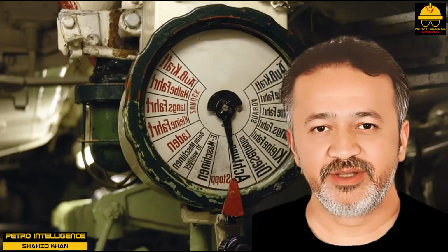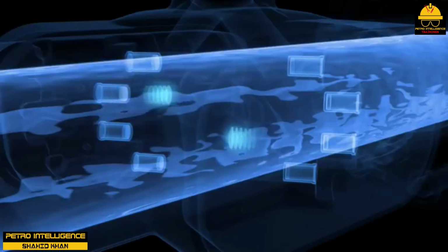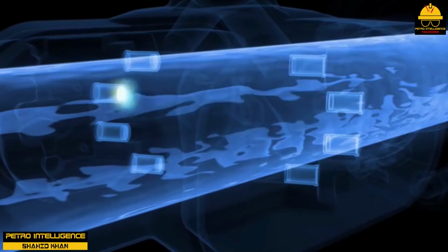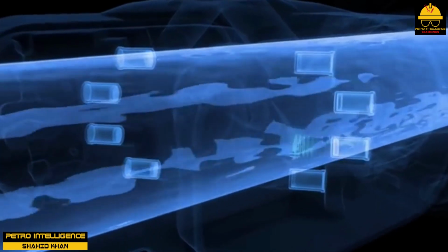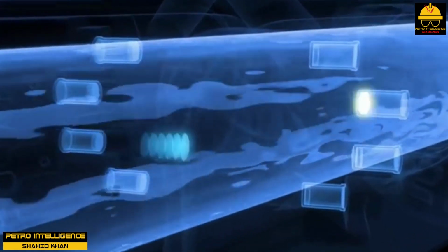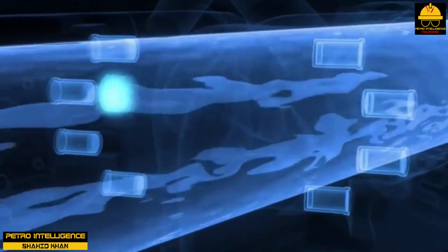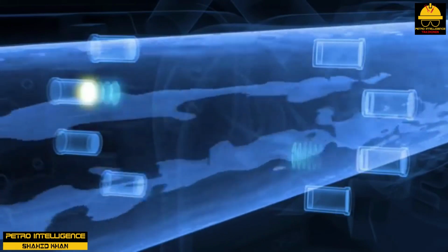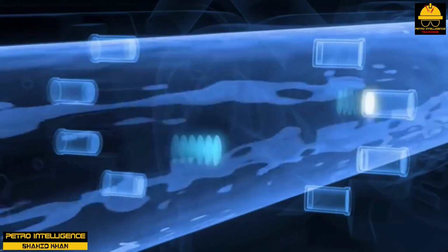Ultrasonic flow meters. Ultrasonic flow meters measure flow rate based on the Doppler effect. A sound wave is transmitted to the fluid at a certain frequency. The frequency of the return sound wave will vary with the fluid velocity. Ultrasonic meters are not suited for clean fluids because they require some type of particle to reflect the sound wave.